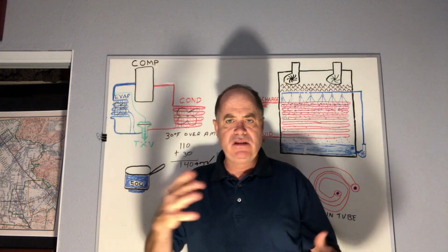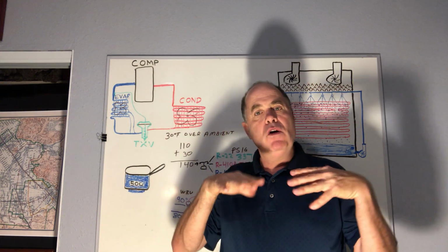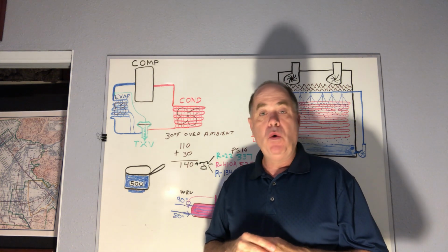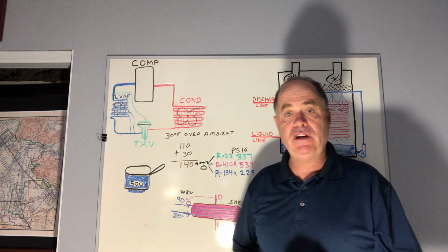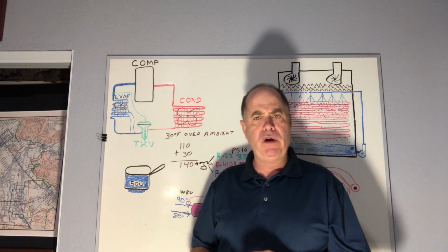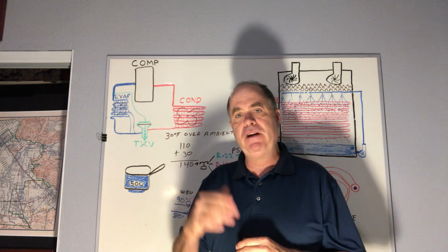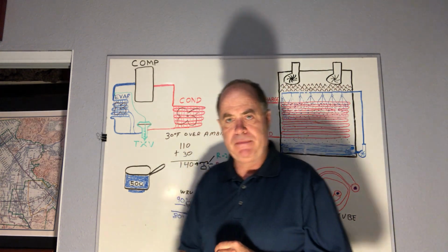And that also leads us to something that I've kind of come up with. You won't really find it in the book: where we can set our head pressure cutouts or test the head pressure cutouts. If you were to block your air-cooled condenser with a piece of cardboard or a panel, will it trip out at a certain point? And maybe you don't know what that point is for any kind of refrigerant, but if you take this principle, you can figure it out, and this is how I do it.